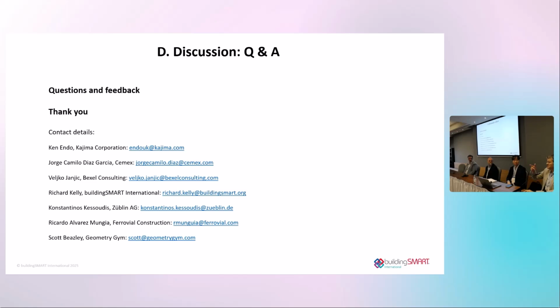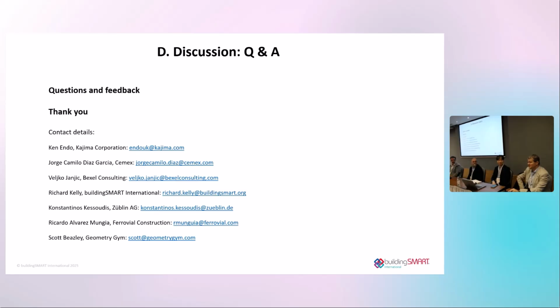If I may say so, thank you very much for emphasizing this. I'm going to mention a couple of things in my presentation, but it's really very important to understand that we need to adjust a model later, and that's one of the very important things for IFC. To go back to Hassan's question, also IFC 5 in the future is to have an incremental model, because I really don't want to update the entire model just because I sliced my slab. I just want to send this information, but I'm going to show you how IFC task and other things can be used, of course.